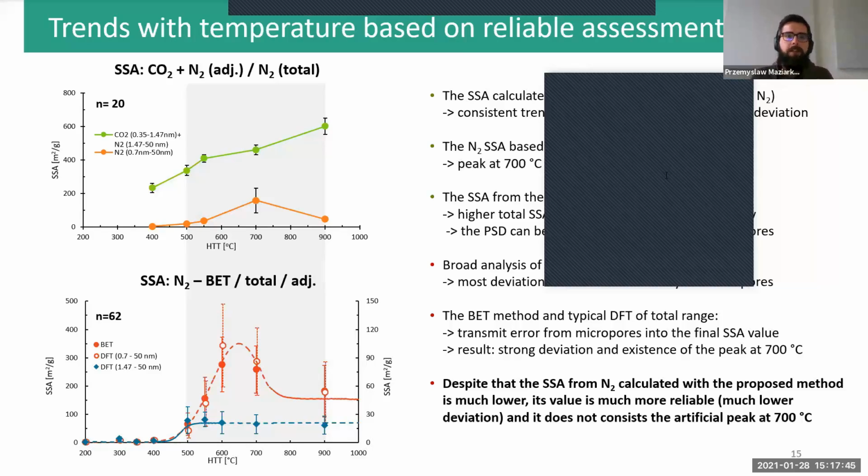But on the other hand, the degas temperature shouldn't really remove the tars that are adsorbed on the biochar, because in typical application of biochar, no one is degassing the material prior to its use. So that is a kind of balance that needs to be obtained. In general, if you have a biochar produced at 350, 400 degrees, a temperature of 180 or 200 degrees is not a problem.